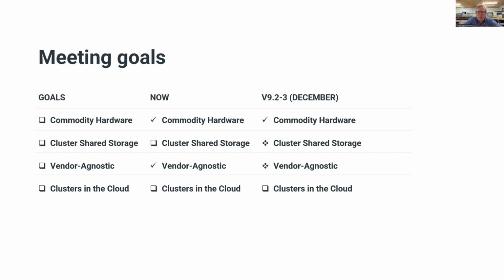Now, unfortunately, we cannot easily support other Fiber Channel adapters. Fiber Channel adapters which have an Emulex chip on them cannot be supported because we do not have the proper driver for them. We also cannot easily support non-HPE QLogic Fiber Channel adapters, even if they use the exact same chip, because what we have found is that each OEM makes small modifications to the firmware on those cards.